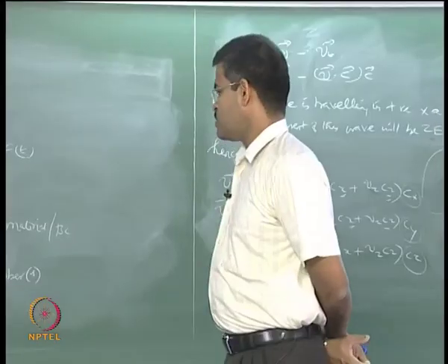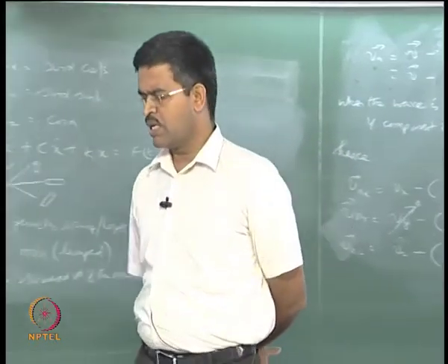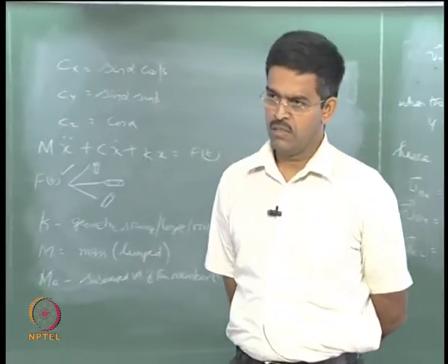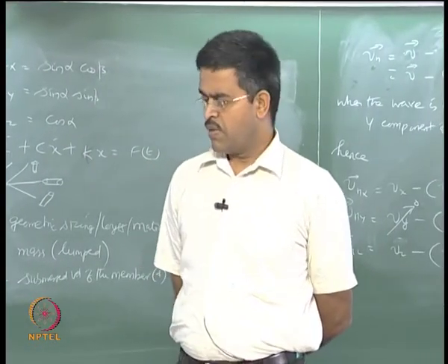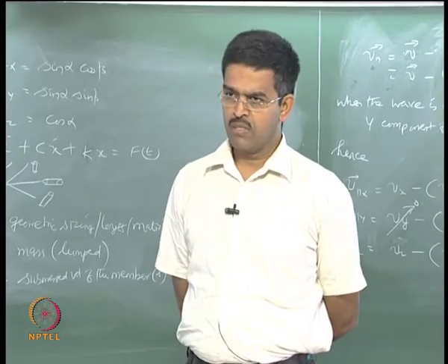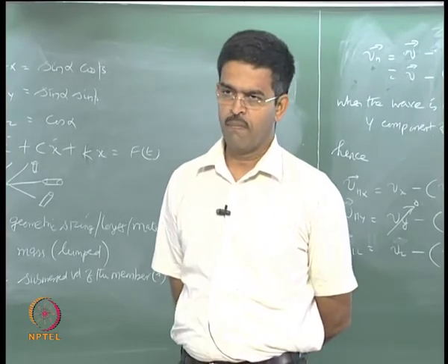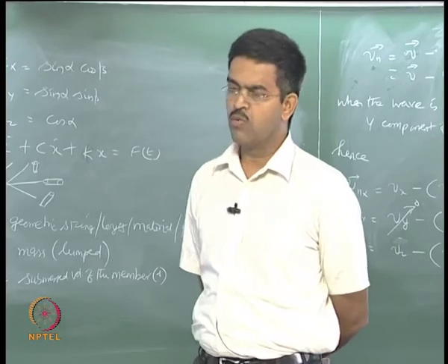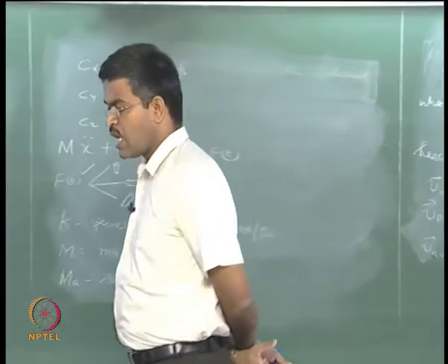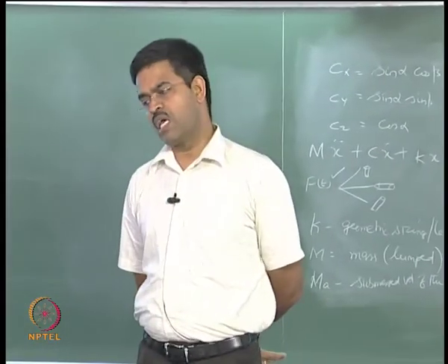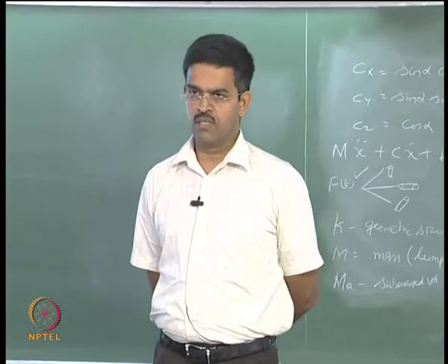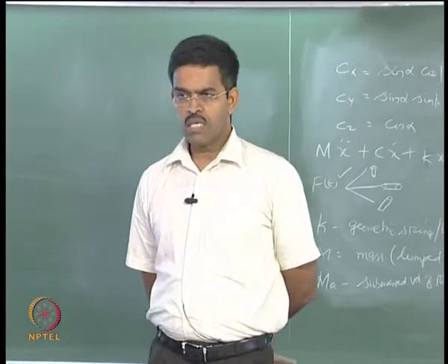So, if the Morrison equation is not applicable, for example, the diameter of the members is very large, they are not slender, we have to account for the diffraction equations, which I will discuss in the next lecture: how I will handle large volume or large diameter members using diffraction theory, which is again an approximation given by different researchers, which we will discuss in the next lecture.